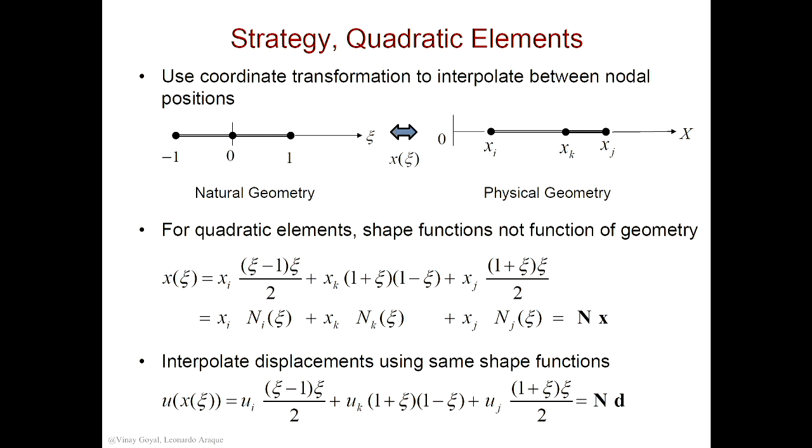Okay. I'm going to put these shape functions in a vector of shape functions like we did before, N, and then x for the coordinates. Notice now how I'm tracking coordinates. I wasn't quite doing that before. So I'm tracking the coordinates very separately here: xi, xk, and xj. If you're curious about what xi, xk, and xj are, as an example, I could have this element go from 0 to 4. Xi in this example is 0, xj is 4, and then the middle node, whatever number I chose to have it. So these are basically numbers.